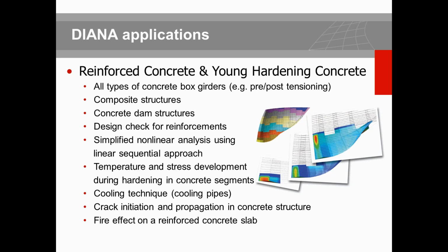With the sequential linear approach, based on the amount of damage that is occurring at each Gauss point, we have a reduction of stiffness for those elements at those Gauss points. So with this iterative procedure and increment of the load, we gradually lose the strength, and you can predict the failure of the structure with a very good prediction with respect to crack bandwidth and the failure mode.